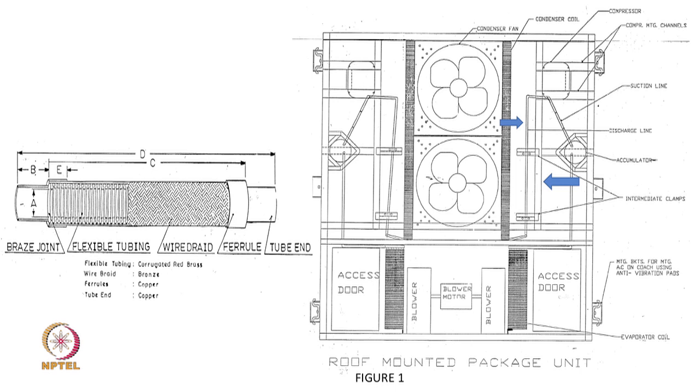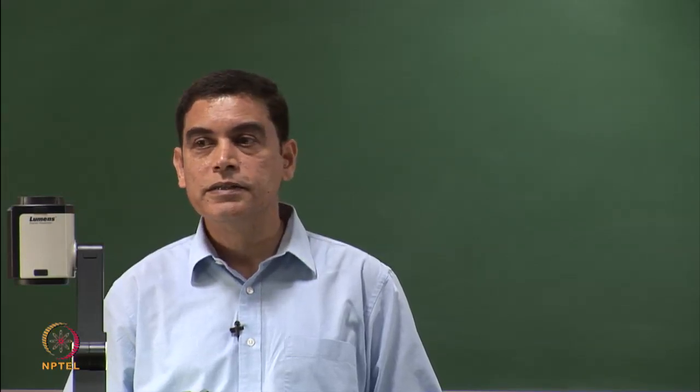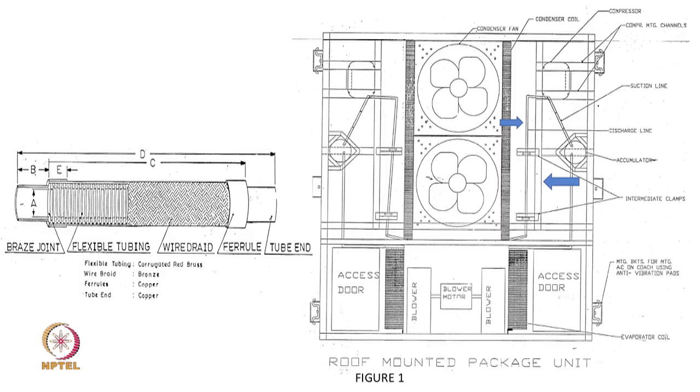Based on that, we made some calculations to ensure that there is no condensate carryover. And if you refer to my notes, 2.5 to 3 is an acceptable face velocity for no condensate carryover. Keeping that in mind, we had the airflow selection done, and the circuit by circuit balance was one of the challenging things, as to how we have the same load per circuit.